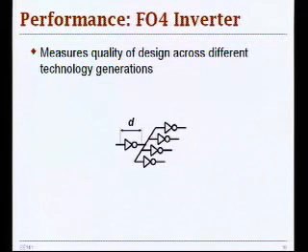this circuit serves as a sort of benchmark to be able to compare various architectures, and evaluate how many stages you have in between pipeline registers, and determine the clock frequency, which is often quoted in these fan-out 4 numbers. So let's say your clock is 10 fan-out 4 inverters or 20 fan-out 4 inverters if you have a different architecture for a different application and so on. So that's an important